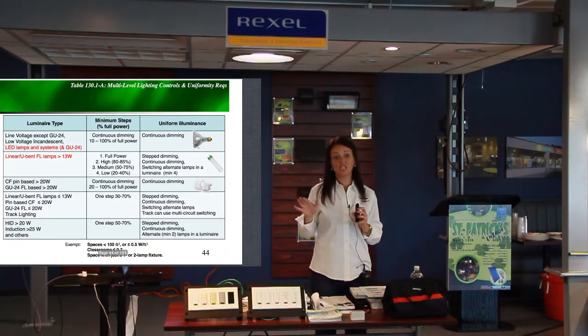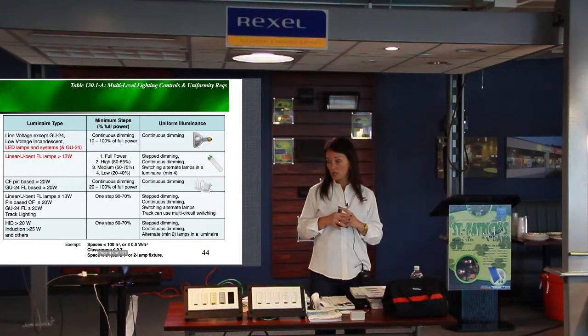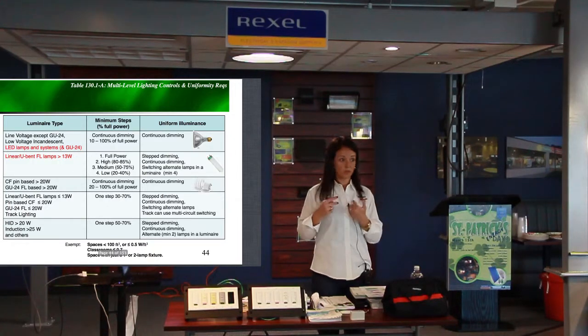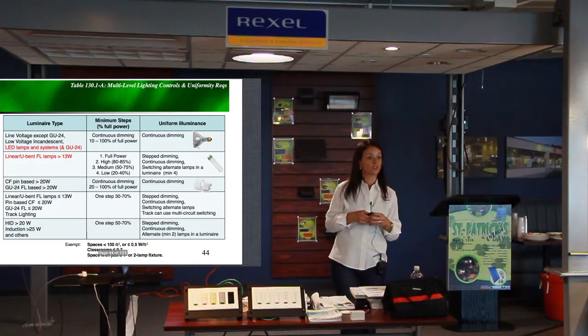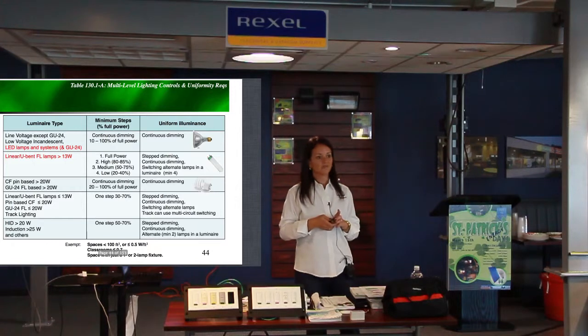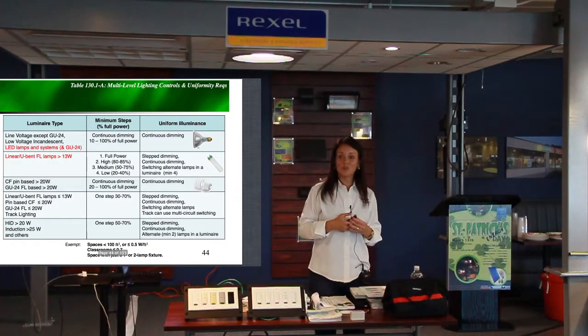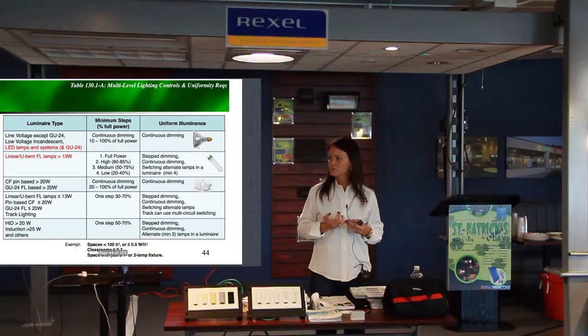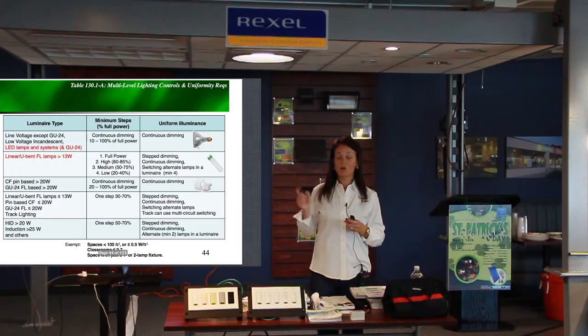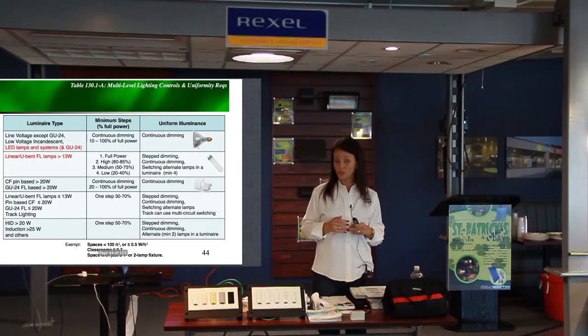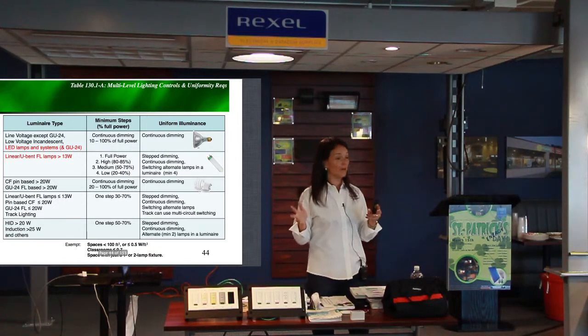For the CEC, 15 years is considered a doable payback. It's not me, it's the CEC. So we know that it's very difficult to consider a 15-year payback. And which number do you think they put in for the dimming ballast? How much is the dimming ballast? You guys sell those? $90, $80, $100. They mention in the code about $28. I don't know where they're buying their ballast, but they're not buying any ballast.